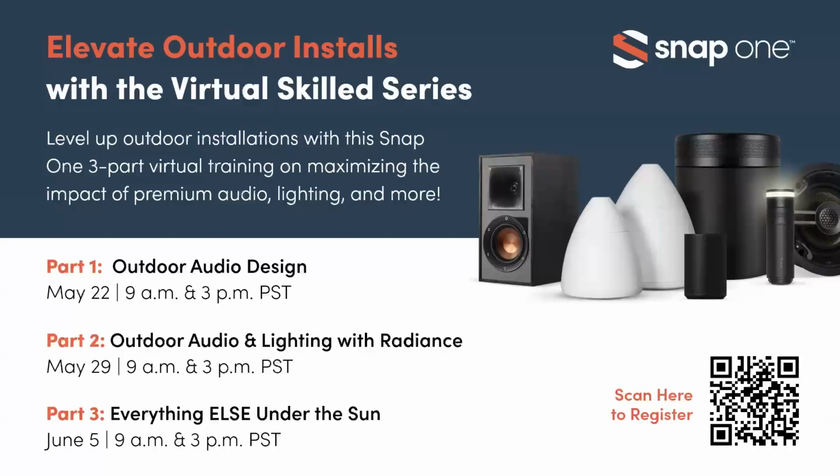Yep. And then a question from Scott here. Will Episode amps ever have EQ settings in the future based on which speakers you set up? They already have them, don't they? Yep. So we have 3 banks of presets, A, B, and C, because the quantity of permutations of speakers and subwoofers that we have outmasses the capability for storing presets in the amplifier. So anyways, yes, we do have presets for the majority of our landscape systems and outdoor systems built into our DSP amplifiers. That's also the case for our indoor multi-channel amplifiers from Episode. We have presets in our Episode Response amplifiers, and in our Triad line, we have presets in our Triad audio matrices as well. So yes, we do have lots of EQ preset settings available.